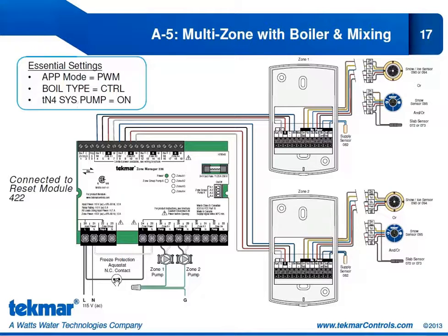It is a normally closed contact, so normally you will have power at Zone 1 and Zone 2, and they will operate whenever those heat relays close for each 654. However, if we do approach temperatures that are near freezing, this normally closed contact will open, and we will not be able to operate the Zone 1 and the Zone 2 pumps. There won't be any power there.